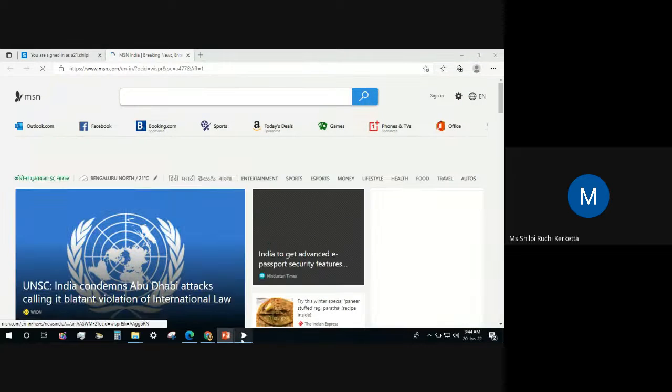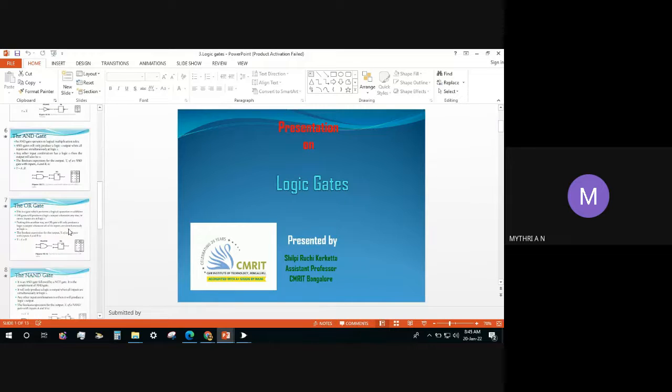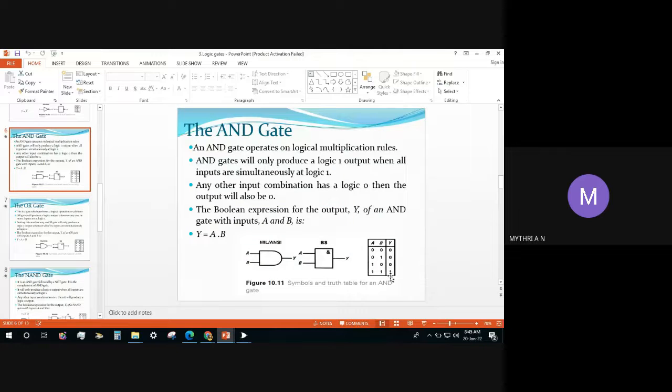You remember the truth table for the AND gate? 0 0 0 1 1 0 1 1. AND will produce the binary multiplication. It gives logic 1 if all the inputs are at logic 1, otherwise the output will be 0. So for 00 we get a 0, for 01 we get a 0, and only for 11 do we get a 1, because it is the product of both A and B.